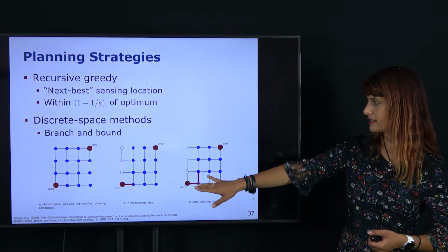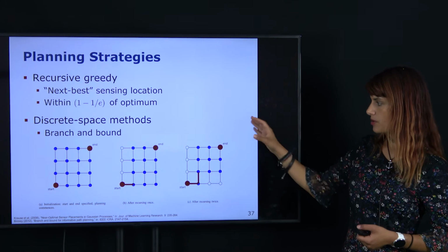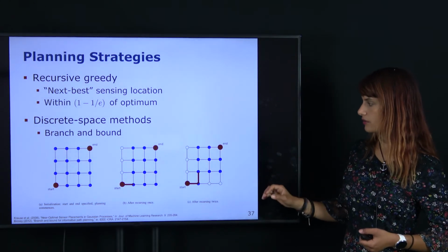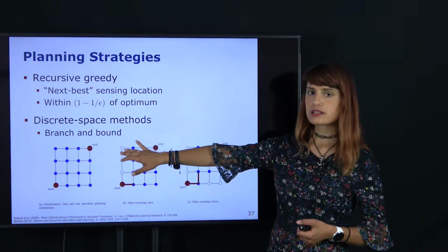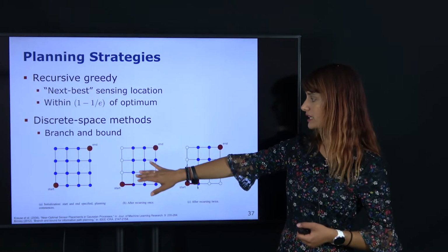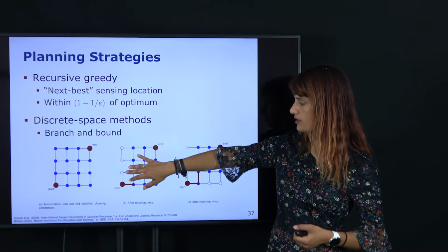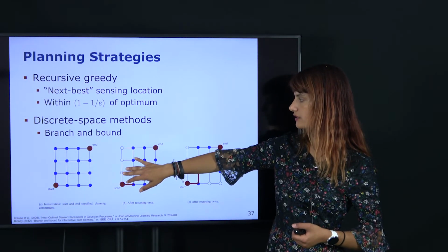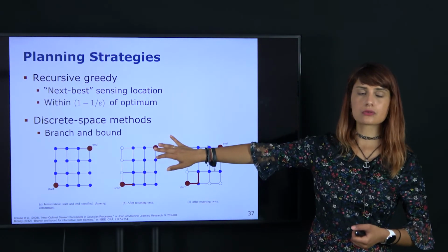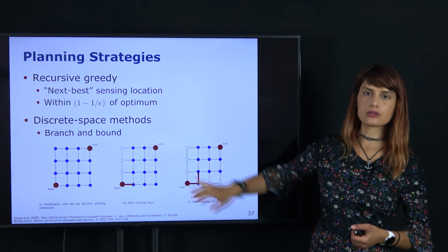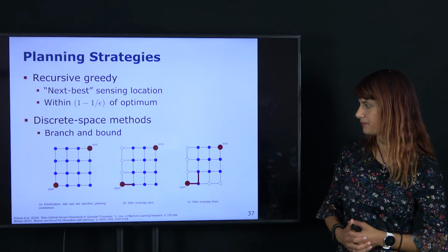So if the robot has taken 1 action, using the branch and bound algorithm, we prune locations that are not reachable. So we cannot go to these 3 white nodes of the graph without using budget that conflicts with our requirement to reach the end goal on the last position.